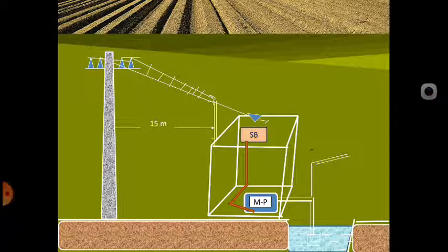And next, what are the factors? You can see here the basic idea of this whole agriculture field. Now you may be given a nearby pole or shed. It is assumed to be 15 meters from the pole to our shed switchboard. From this one, 3-phase supply is available, RYB and neutral. Generally we take a 6 square mm aluminum wire as the service wire, twin core.